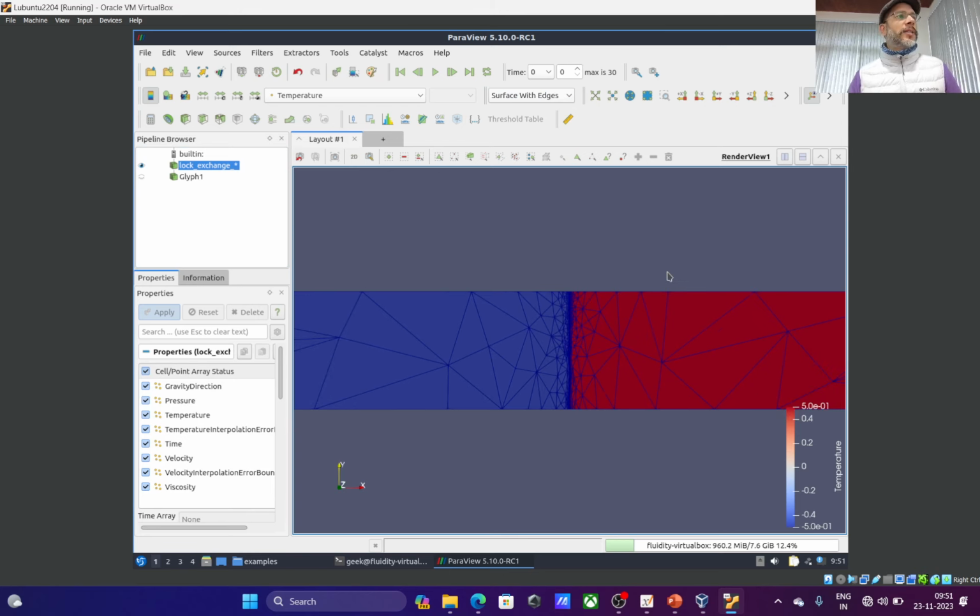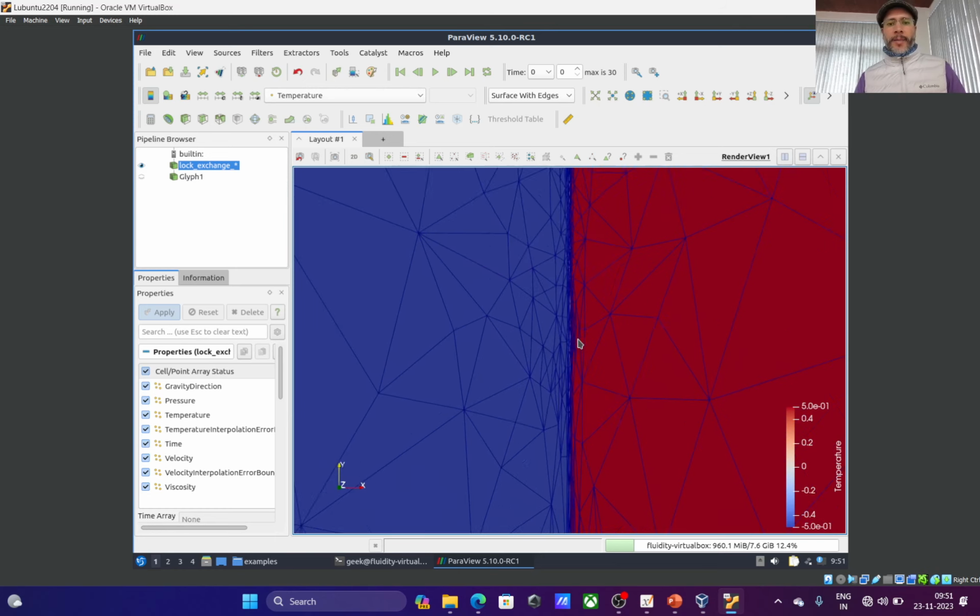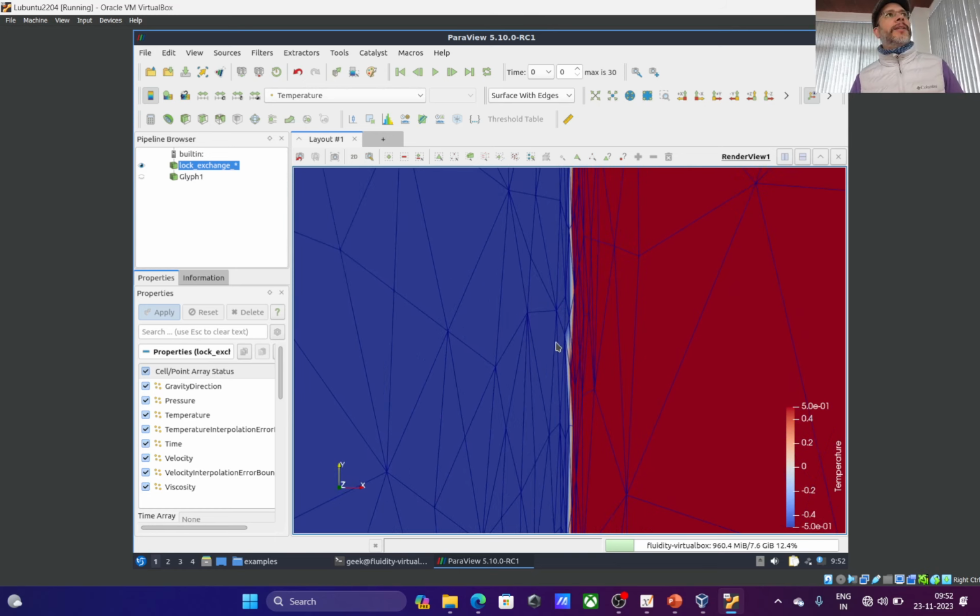So the mesh actually is quite non-homogeneous. It's not that homogeneous mesh that we had, right? It looks quite coarse in this region, and near the boundary, it actually is really fine. I'm not sure if you can see that clearly, but they're very elongated elements. So this is an anisotropic mesh in the sense that it has a directional preference.